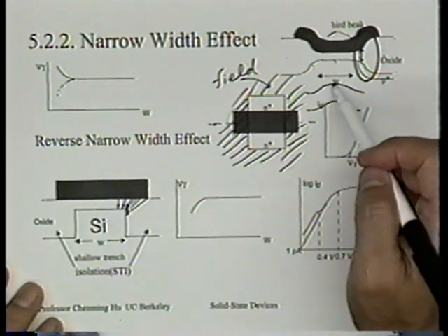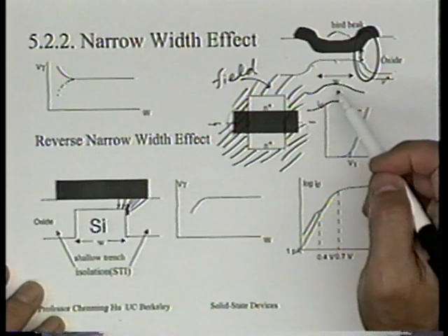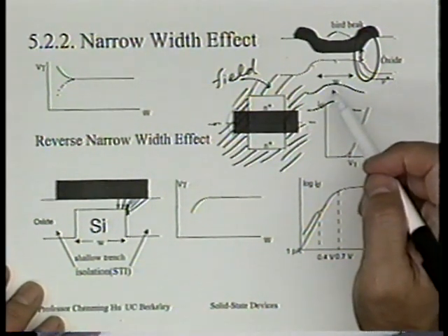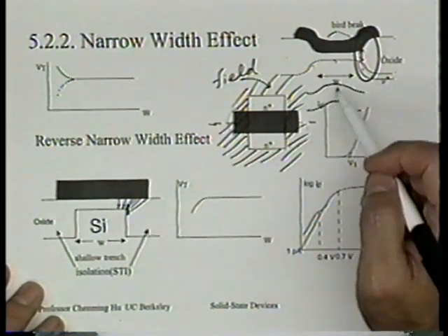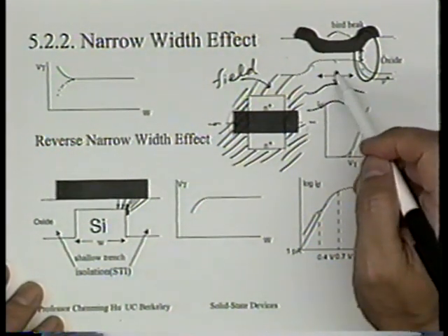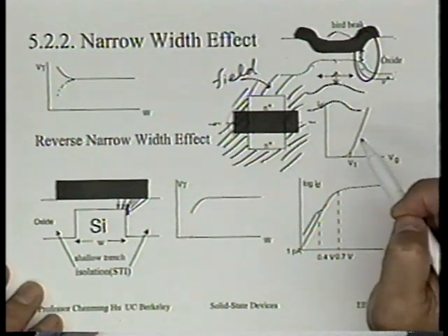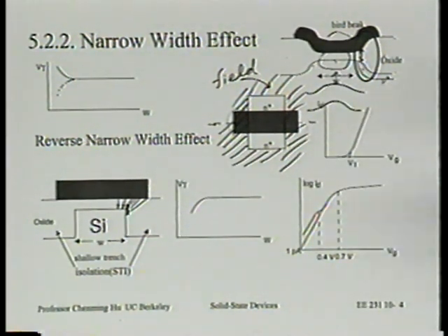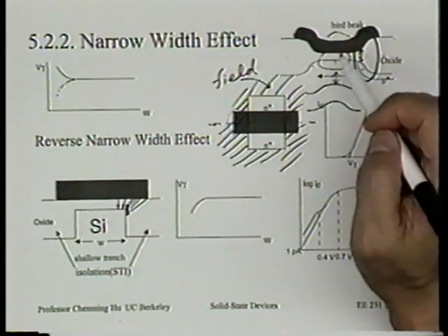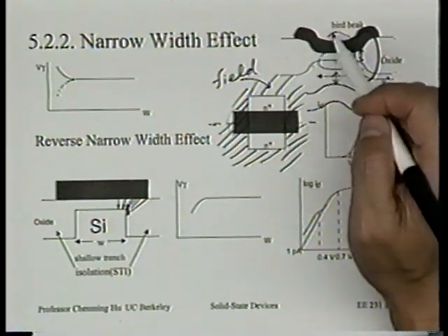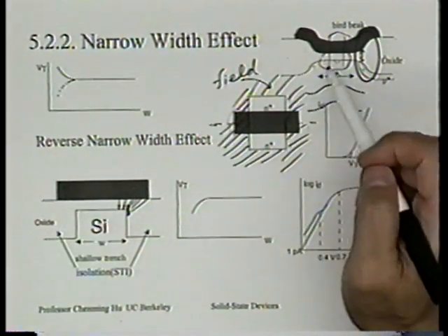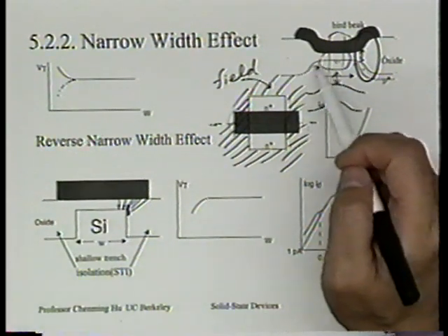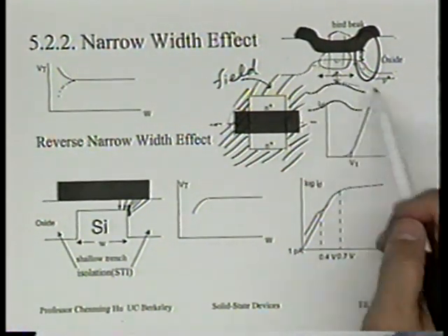When the energy band diagram is pulled low enough, when the barrier is pulled down enough, you get threshold voltage. Is that right? So if these two boundary conditions are now pulling the band up, then even the threshold voltage of the center portion will rise. You see what I'm saying? In other words, the threshold voltage is not just simply a function of the local doping concentration. It also has to do with the doping concentration around it, because you have to solve the Poisson equation in this W direction.